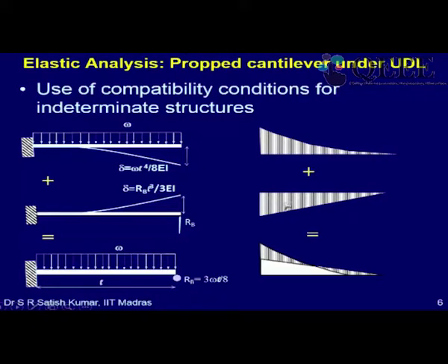Now if I add these two bending moment diagrams, I will get the net bending moment diagram. So I have shown this inverted downward triangle upwards just to remove it, because we have to subtract it. So here from the total of the first case, this gets subtracted and what remains is the shaded part. But after this point, the second one has more value than the first one, so it goes upwards.